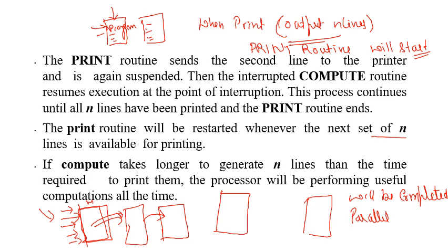So if the programming is done using a polling method, each time the processor has to waste time roaming around checking for these conditions. The two methods we follow are mainly the polling method and the interrupt method. In case of the interrupt method, only when there is a fire it will send the signal, and until then the processor need not check for any of the conditions of the sensors. Whereas in case of the polling method, each time it completes one cycle, it has to check for the sensors. There are a lot of disadvantages of the polling method that we will discuss in our coming slides.